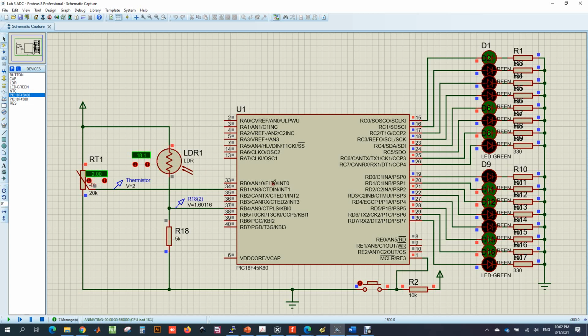now 3, 2. Okay, and the analog input from the LDR photoresistor is displayed on port C, only the high byte, the higher 8 bits of the ADC result from the 12-bit conversion, that is displayed on port C.